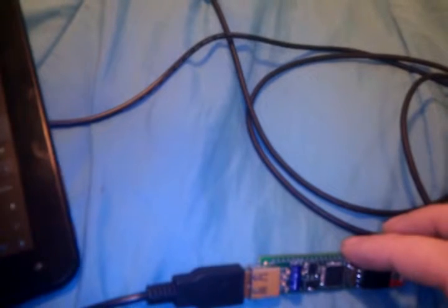Even if you want to do servo controls, all you have to do is hook up the data pins to here, feed the servos 5 volts, and you can do whatever you want. If you can do a servo, you can do a motor controller, you can do a robot, you can do a number of things. If you want to connect ultrasonic sensors to this, you just do. They can be read, it can output. You can create your own device as a file that just outputs, again, numbers, for example, and your application can read it.